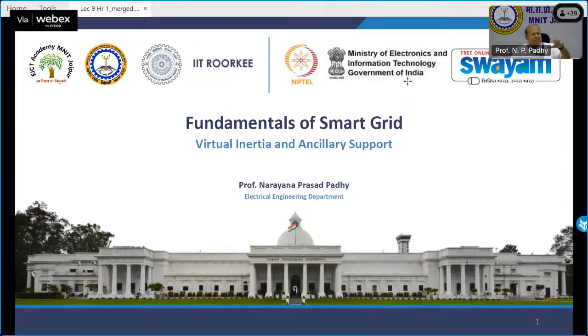Am I right? There is some inertia available that people can extract, not 4 megawatt, but at least 0.5 megawatt, let's say. So if you ask for 4, it will say I can provide you only 0.5, sir, and give me 5 seconds to give you 3.5 megawatt after some time. And that is where the concept of virtual inertia came into action. All right, so hope everyone understood what inertia is, what the challenges are, who is responsible for inertia, and hence the importance of virtual inertia.